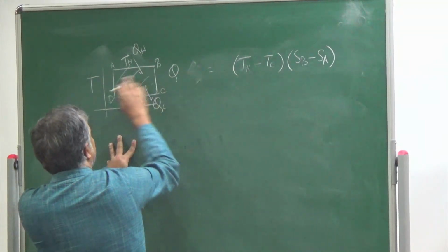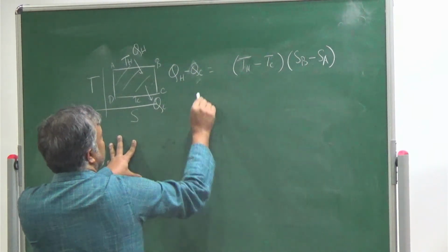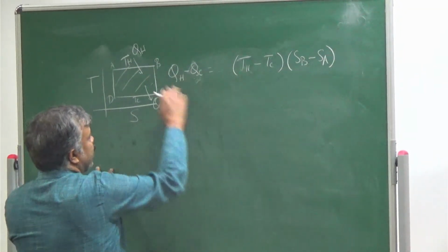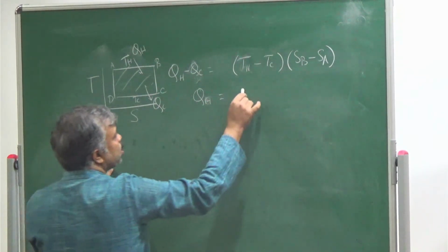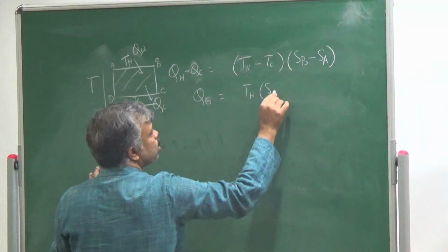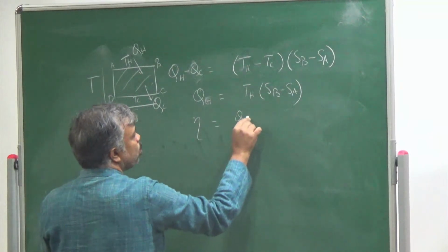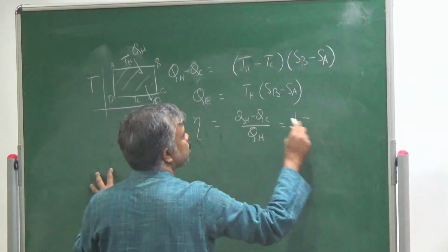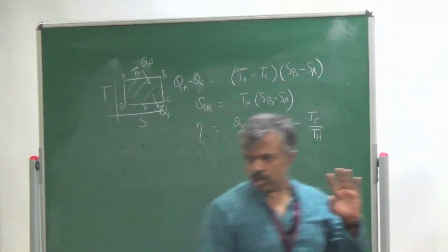You see these are the adiabatic or isentropic paths, so no heat transfer. So QH minus QC. This is the heat that goes out of the cycle, and this is coming in. So this is the net one, and then you have Q. What is the input? It is then QH. So the efficiency is, this is the simplest thing that we have done long back.